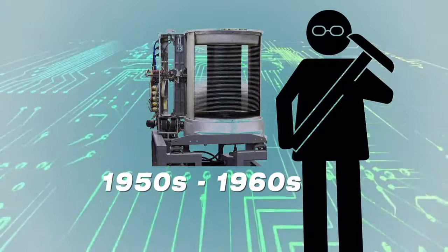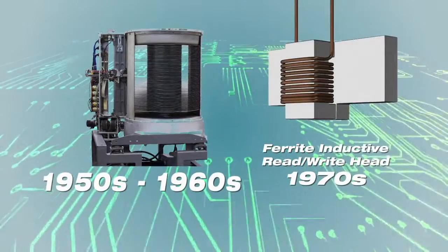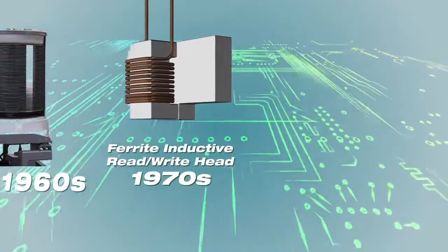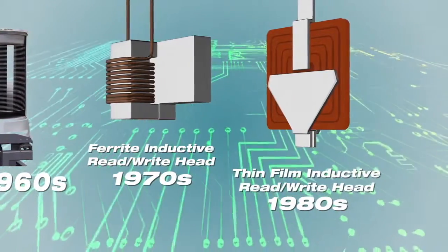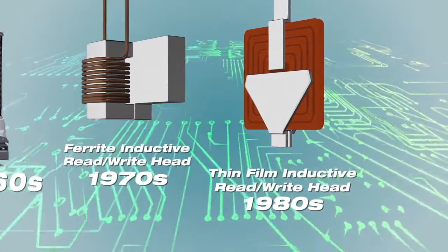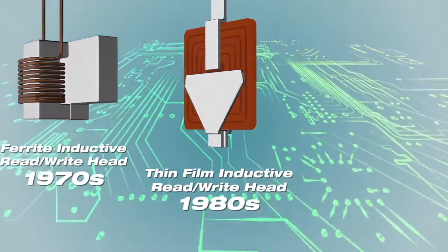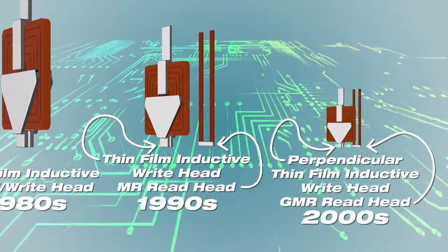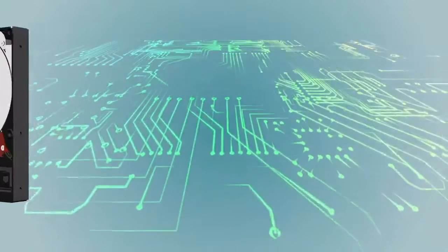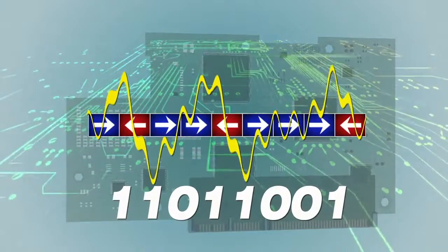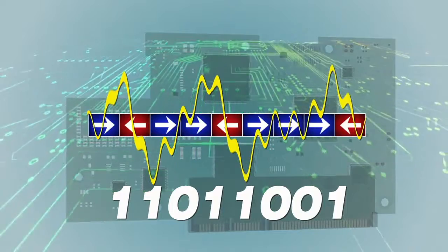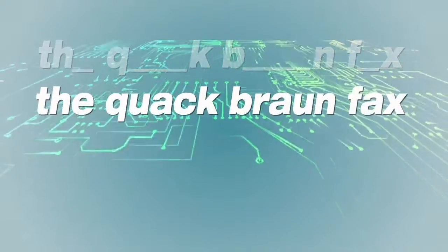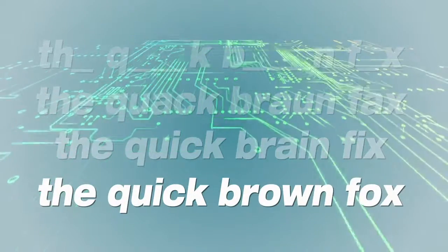This amazing advance in storage capacity wasn't just a matter of making everything smaller, but involved multiple innovations. A technique called the thin film lithography process allowed engineers to shrink the reader and writer. And despite its size, the reader became more sensitive by taking advantage of new discoveries in magnetic and quantum properties of matter. Bits could also be packed closer together, thanks to mathematical algorithms that filter out noise from magnetic interference and find the most likely bit sequences from each chunk of readback signal.